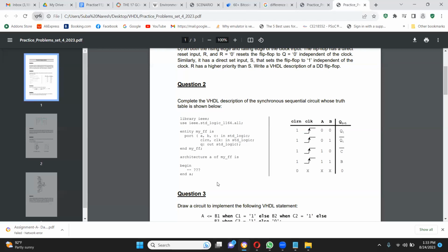So I get what you're saying. So you want to use the stupid way. I'm thinking about, is there a smart way? Okay, and if B equals 0, then it's Q(t+1) equals Q(t). I think you don't have that kind of variable in your port declaration. You just have Q, right? Can you see the entity port declaration? You don't have Q(t+1). So how will you do that? It is very simple. Q equal to Q. Your next Q is going to replace your previous Q. Simple.